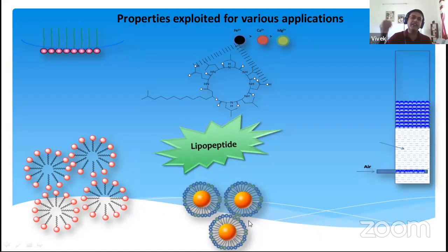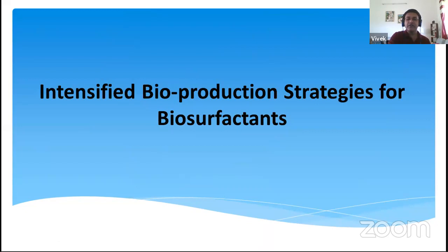In fact, there is another way of injecting this compound in the form of stable micelles. Upon injection, these micelles, out of their inherent capacity, allow the entry of the oil into them, forming swollen micelles, which is what is being exploited in another type of recovery called microemulsion based recovery.